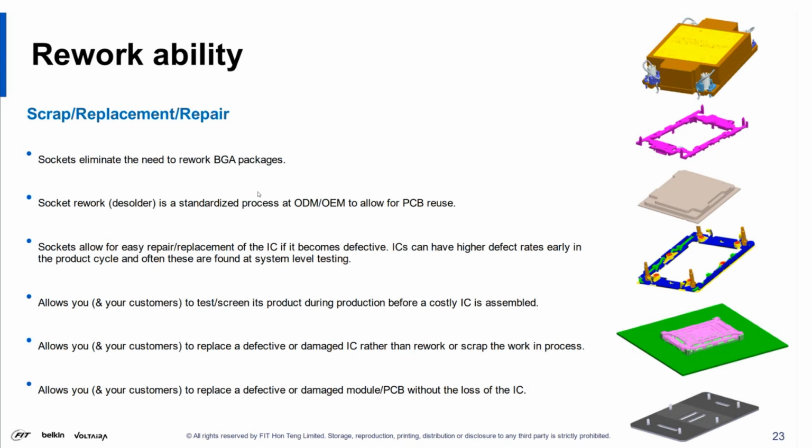Reworkability. Sockets give you some advantages here from scrap replacement repair. Sockets eliminate the need to rework a BGA package from direct attach, so you don't have to worry about that. Socket rework or desoldering is a standardized process at OEMs and ODMs and has been for several decades to allow for PCB reuse. So there's a standardization if there is a defect or a problem with the socket due to damage or some other, it's easily desoldered and replaced with another socket, standardized today.